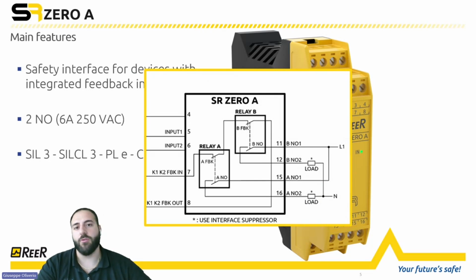This depends on whether you need another signal, a normally closed signal or not, because you also have to consider the electrical diagram that we have inside the module, the interface. So if you need one more normally closed contact, then you can go with the SR0. If you just need to connect the normally open contacts to drive the actuator or to go into external contacts, then you can go with the SR0A.